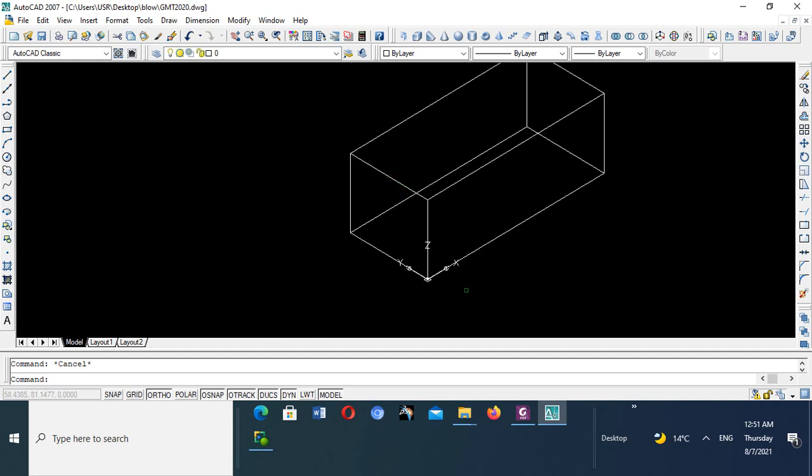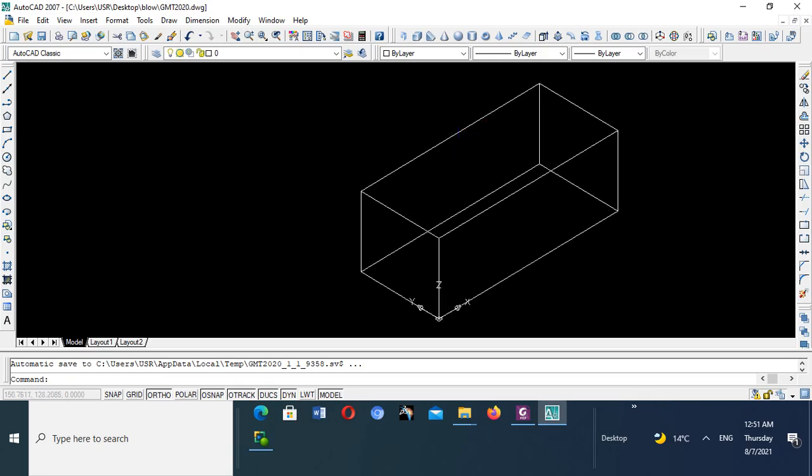So I want to transfer this coordinate system, the origin, from this point to that point, for my convenience when I'm drawing any feature in this top plane. My 0 is here, it makes life easy. If my 0 is here, I will have difficulties in writing the Z coordinate. So I want it to be here.